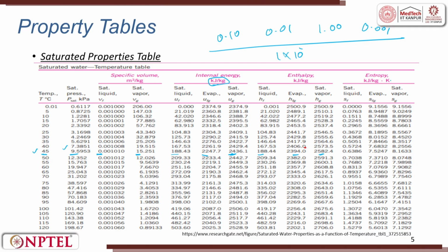When we talk about entropy, you will see that you will have 0.063, 7.5 and 8.1 for saturated liquid SF, SFG and then saturated vapor SG, you will have these values. So, here if you see the intermediate form is the two phase mixture. When in the examination problem we give a two phase mixture, you are supposed to take this value.